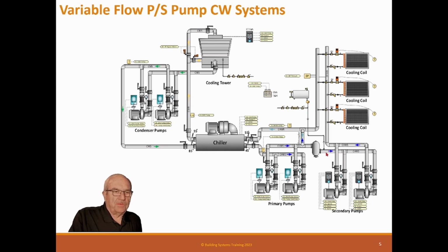This comes over to the suction of the pumps, and it really should be the suction of the secondary pumps, is where it's designed to be, okay? So what happens is that when the system is off, this provides enough water pressure to push the water clear to the top of the pipe. If this is not set high enough, then when it's off, the water will seek a level down here somewhere, and this will be under vacuum, and will actually pull air out of the water to fill this